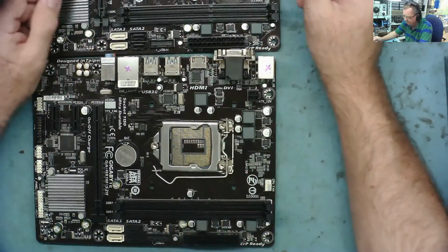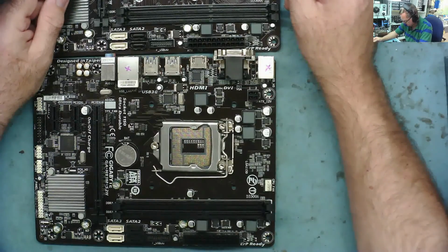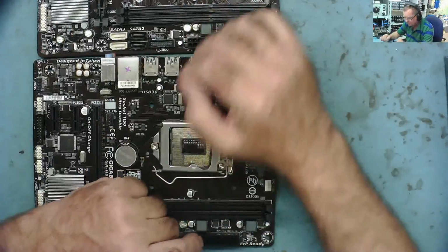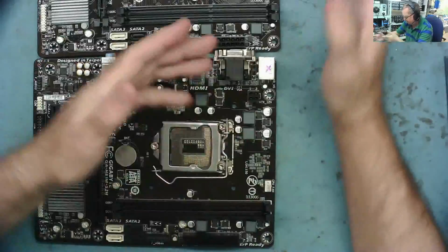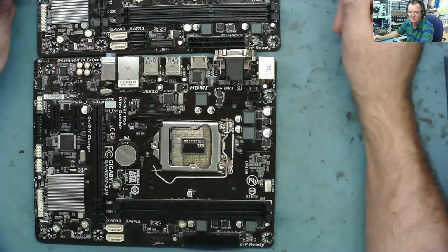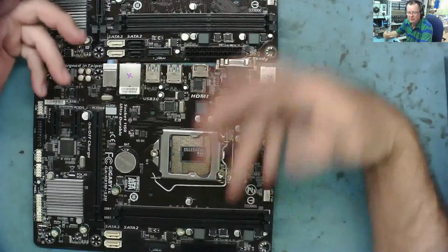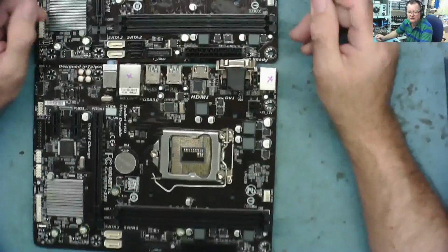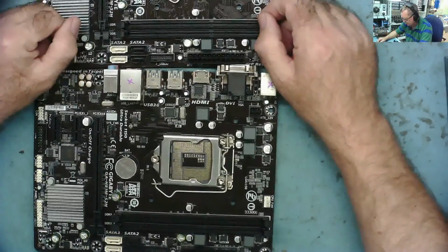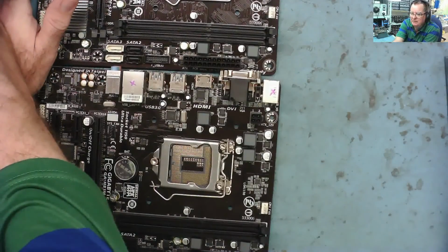I've got a couple of bench power supplies here. I've got technically three, because one's dual and one's a single. I'm wondering, is it possible to power the board from a bench power supply and effectively make it switch on when the green wire is grounded? Then on the bench power supply I can see the current being drawn on each voltage rail, and I can also set them to trip out, like a current limit. Let me have a think about that.